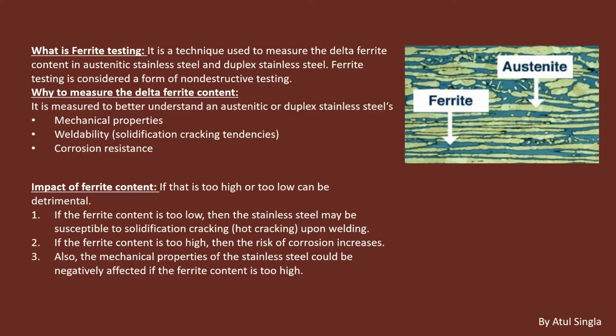If it is too high, then there may be a different impact. If it is too low, then it can be a different thing. If it is too low, then stainless steel may be susceptible to solidification cracking, because we are going to do some welding, there will be different temperature zones. So at a particular time there may be hot cracking if the content of ferrite is too low.